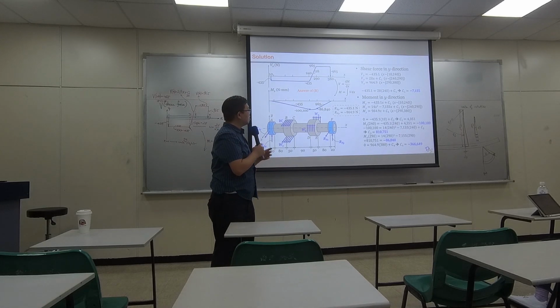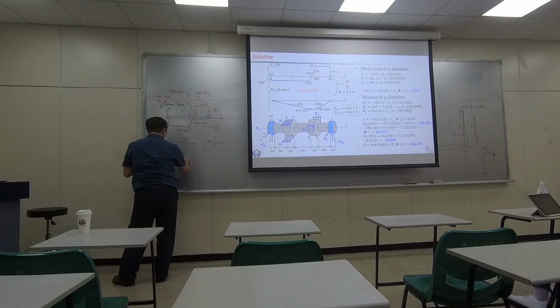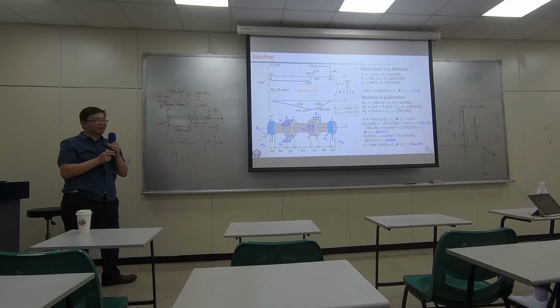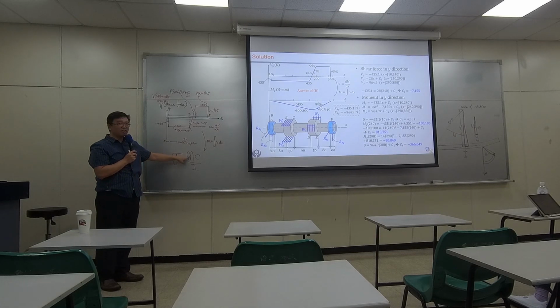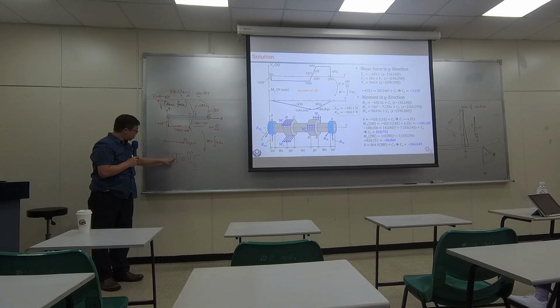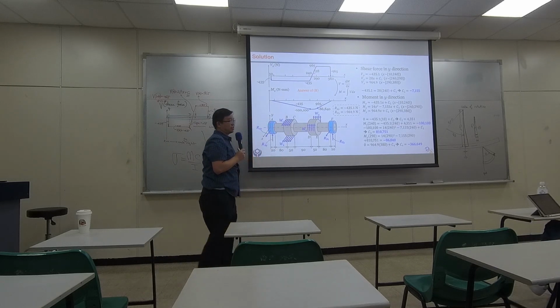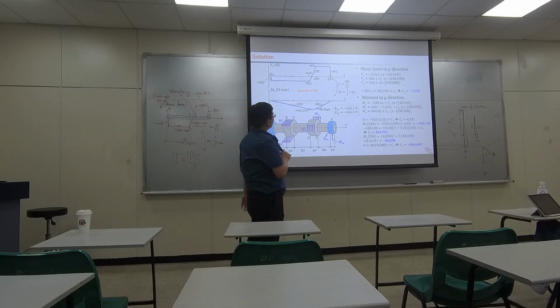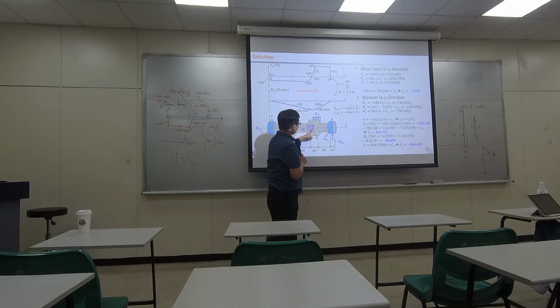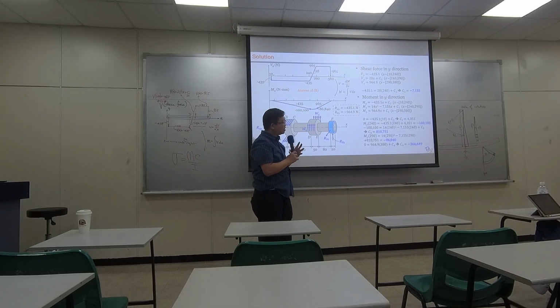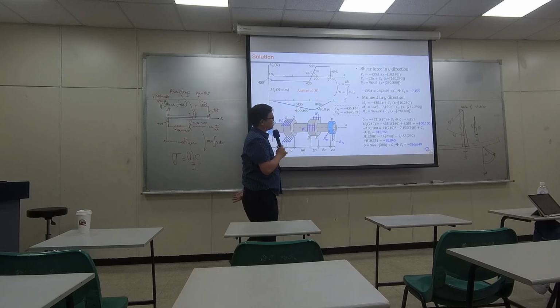And remember, our stress equals moment times C over I, right? So at that particular position, this value is the largest, C is the same, I is the same everywhere. So at that position, the moment is the largest, so over that particular position, we have the maximum stress. So if I really want to break this shaft, it will crack or permanently damage at that particular position.